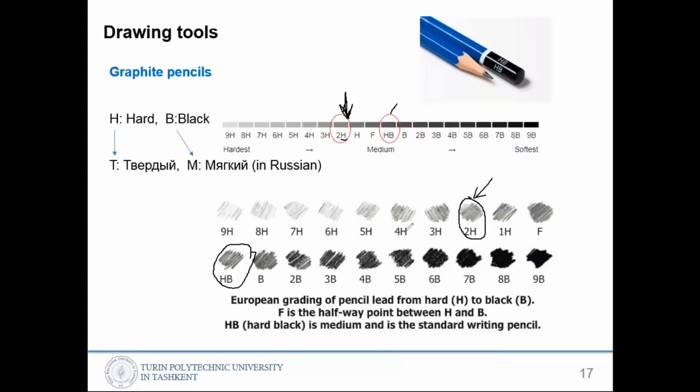So you draw your shape with 2H. There will be thinner lines, and it's easy to erase and easy to change, so it makes no mess. After everything is fine, you can refine it using HB, just redrawing it with a continuous thick line. You use 2B as well. After doing this, be careful, because you can damage your drawings.